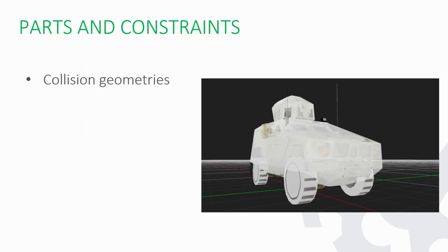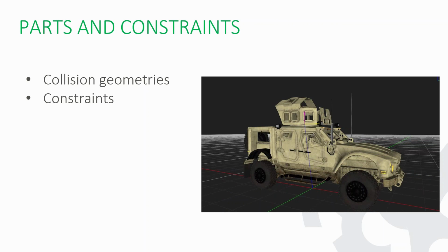First, we set up the collision geometry. The hull itself is a part with a convex shape placed around it. We were fairly generous with the collision geometry. There is no real purpose in having something that closely conforms to the shape of the vehicle itself. As long as it's reasonably close to the hull, for a driving simulator, it will be enough. The wheels themselves were set up via the vehicle system, so we created a specialized template. I'm going to talk about it a little further.